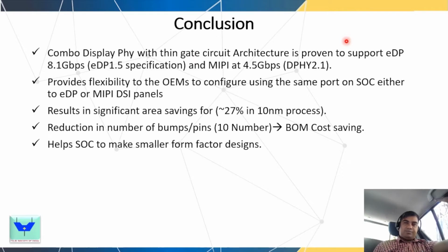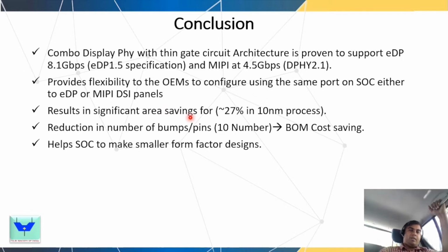So we have the final conclusion. The combo PHY met the purpose of supporting the two IPs with the same IP, and it met all the compliance requirements. The advantage is that this provides flexibility to the OEMs and also the SOC to configure the same port on the SOC either to eDP or MIPI. So that's a great flexibility. They can decide it at the last minute also.